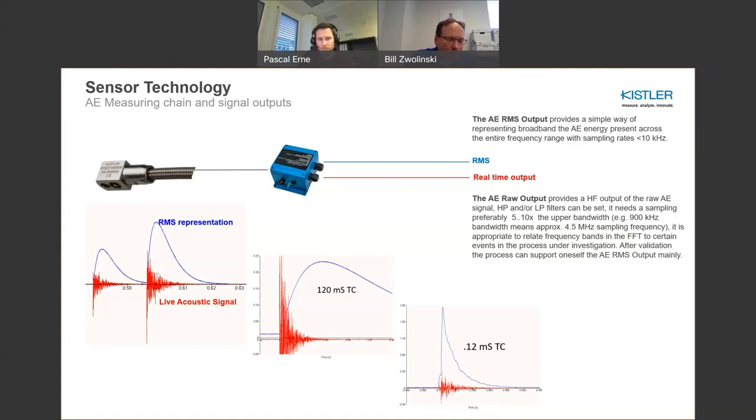It peaks up here and goes down. Same thing here, and same thing here in this RMS. So by picking short or long RMS time constants, you can better tailor your output voltages to represent the detection of the AE event that's of interest, and that's often a very powerful tool.